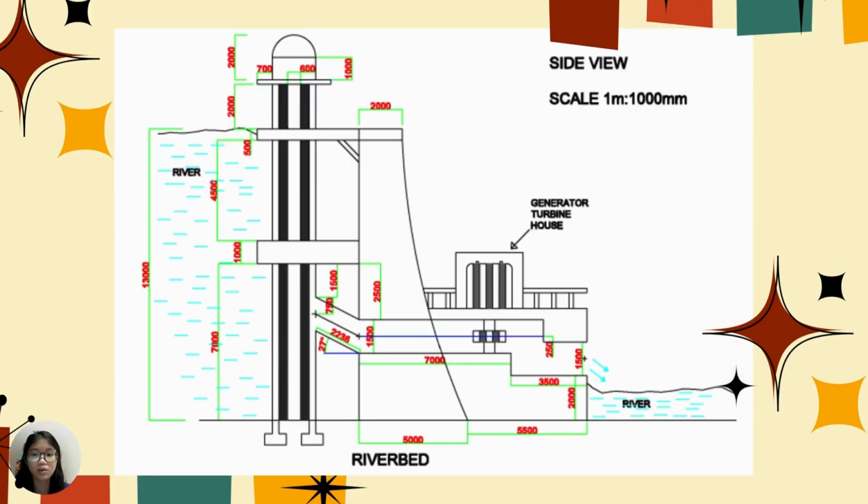First, we can see we have a plan view here. Our dam is designed in a small river between the mountains, and we designed the hole that the water goes in to be deep under the water, about 8.25 meters, with a slope to the horizontal pipe of 27 degrees. We have two elbows at the end of the pipe to decrease the height between the pipe and the land, and we have a generator turbine house behind the dam to generate electricity.